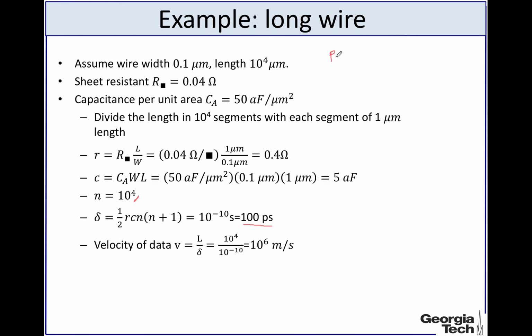Now remember, for the previous case our L was 100 microns and the delay was 10 femtoseconds. Now we have increased the length by 100 times, but our delay has increased more than 100 times, and this is the essence of the problem: as we go to longer wires, the delay also increases significantly.